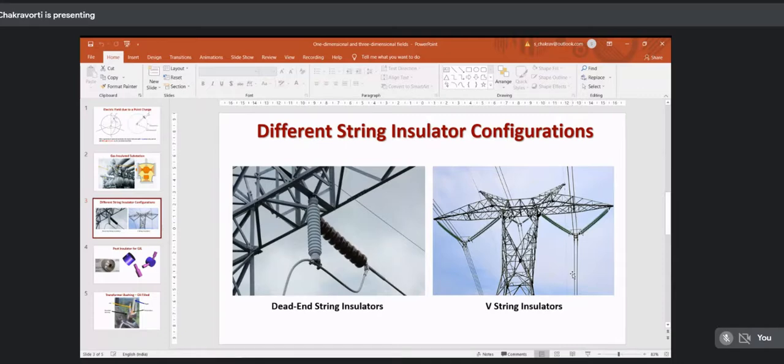Because this is the practical information, the practical life. Any other suggestion? Yes? Bundled conductors. Correct. Now you have given the correct answer. It is not a double circuit line, right? You can see there are three phases here, you can look at the V. There are three V's which are supporting three phases, R, Y, B. But this is called bundle conductor system.